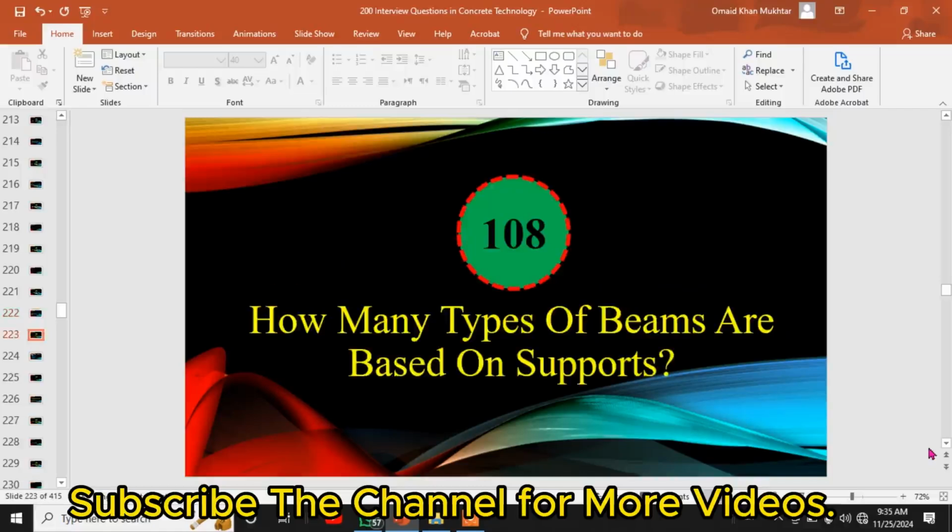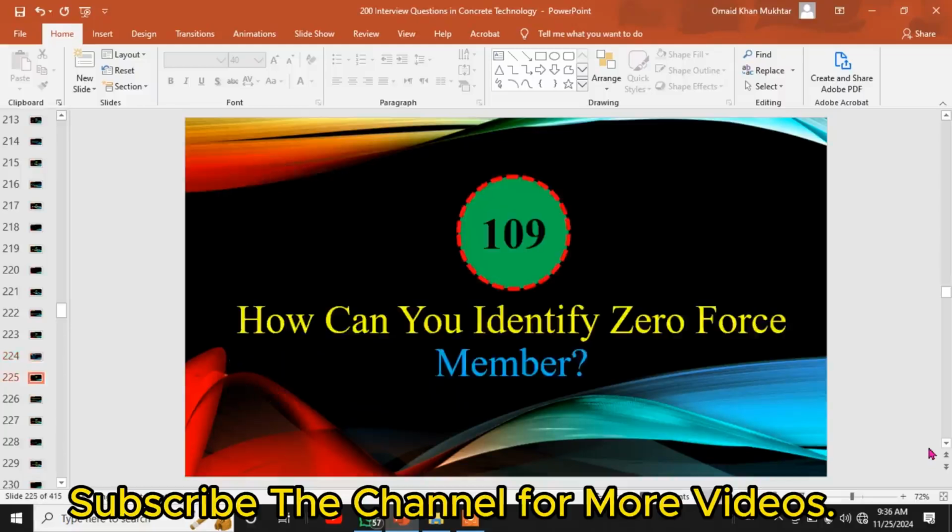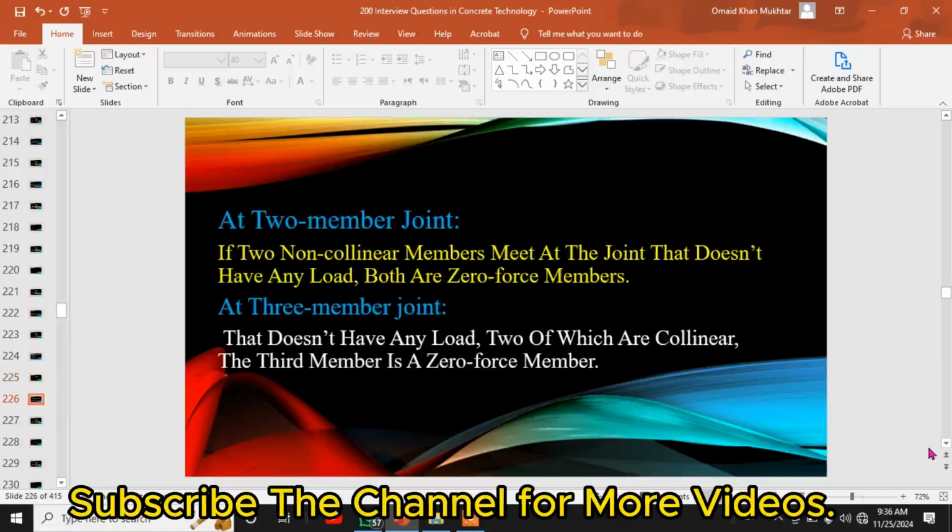108. How many types of beams are based on supports? We have the following beams based on supports: simply supported beam, cantilever beam, overhanging beam, continuous beam, fixed supported beam. 109. How can you identify a zero force member? A two-member joint: if two non-collinear members meet at a joint that doesn't have any load, both are zero force members. A three-member joint that doesn't have any load, two of which are collinear: the third member is a zero force member.